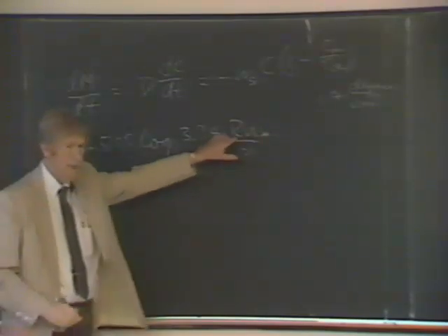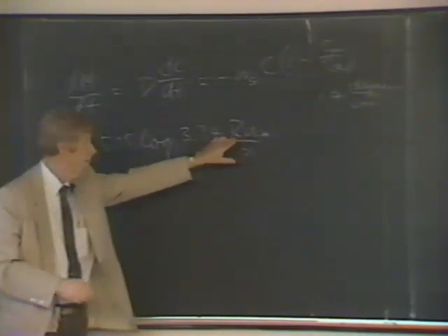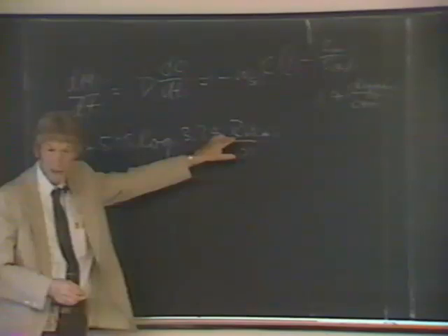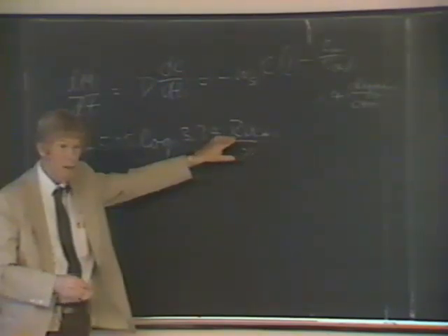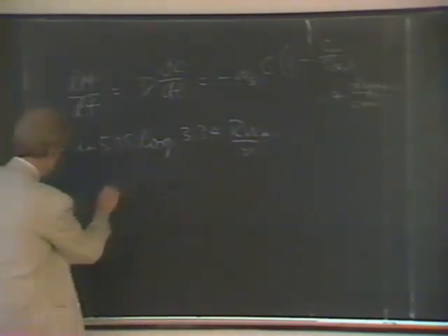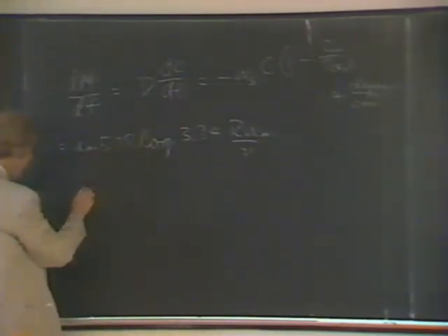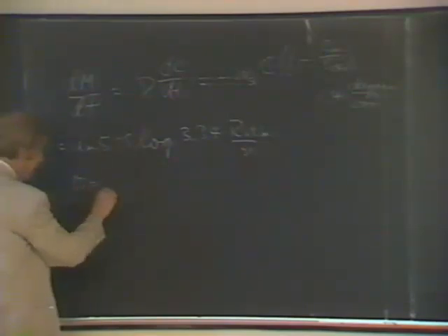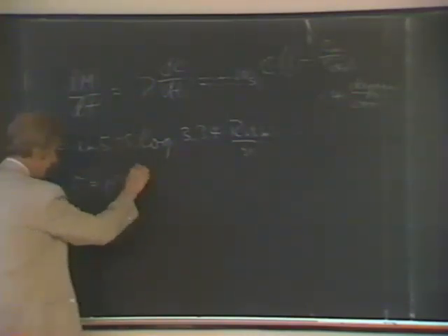And since I didn't give you any cross-section, you might take the depth, and most everybody did that. Or if you knew the cross-section shape, you could calculate R. Then find U star by trial, and then the shear stress on the bed is rho U star squared.